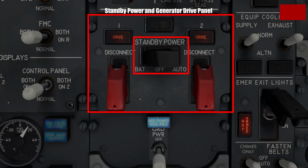Let's first cover this black guarded switch in the center and its associated light. This black guarded switch is the standby power switch, which is normally left in the auto position and is rarely manipulated by pilots during normal operations. The standby power system powers the most important electrical components that receive power through the standby bus bars or buses, as well as battery buses during partial or total electrical failure, so they're extremely important and better to not be messed with. The light on top illuminates when the standby power is manually switched off or if there's a fault with the system.